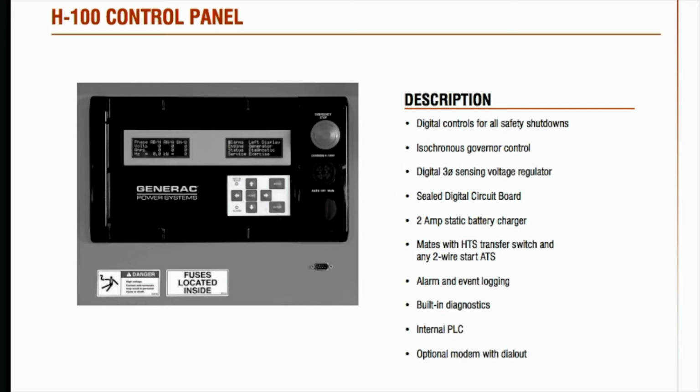So in terms of features, you have local and remote connection to a PC for GenLink DCP connection, and interface with up to 2 remote annunciator panels. The display is very customizable. It does have a built-in frequency and voltage controller. You have communication via standard CAN bus and Modbus protocols. Like I mentioned before, the programmable I/O channel properties, programmable alarms and warnings, alarm and event logging with time stamping, and parameter logging and trending, both to file and graphical.